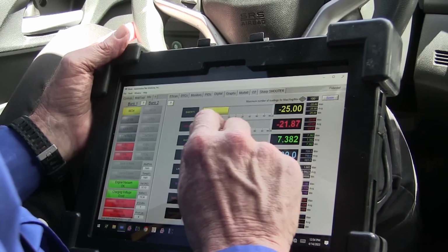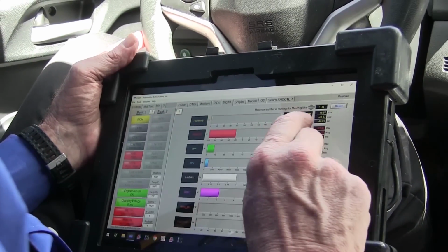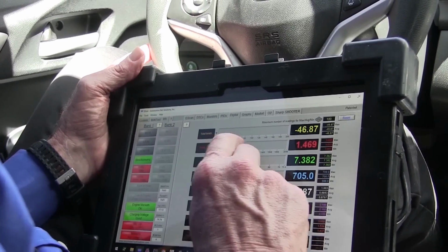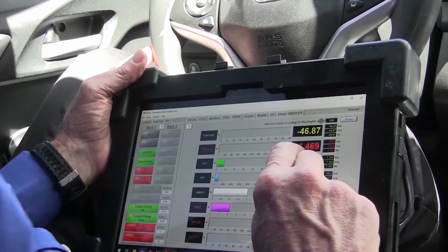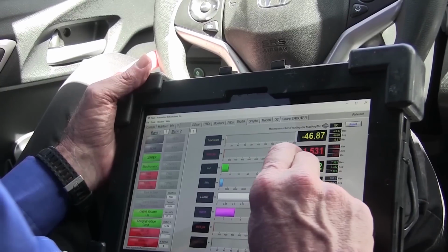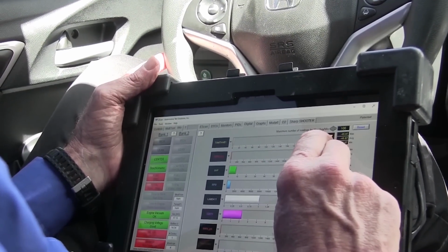So we're going to put total trim on the top, minus 46, and we're going to put the grams. I've got a 1.5 engine, I'm reading 1.5 grams, so this is about what I would expect the air to pump right now, but I'm taking away 46% of the fuel.